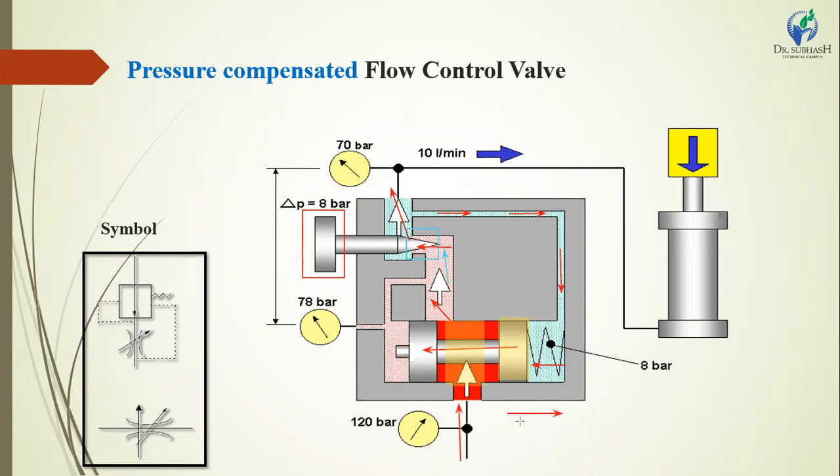That means pressure compensation. If the pressure goes low, the spool moves in the right-hand side direction. If the pressure at the outlet increases, whenever back pressure is generated, the spool moves from its right side to the left side and closes the inlet hydraulic pressure into the FCV. It works on a pressure basis and gives safety against higher pressure in the working system of the hydraulic circuit.